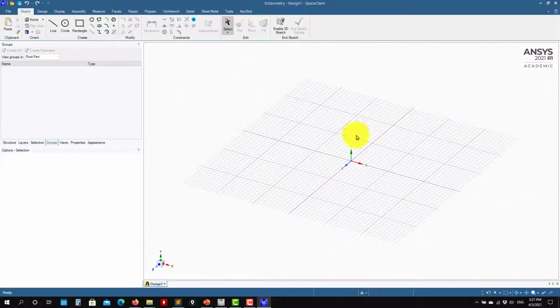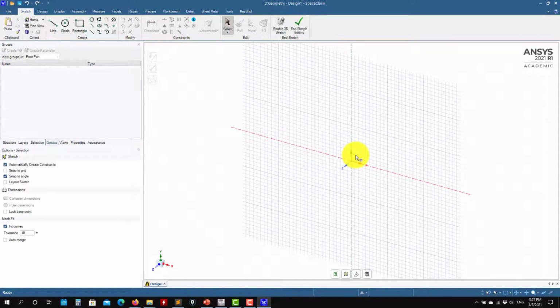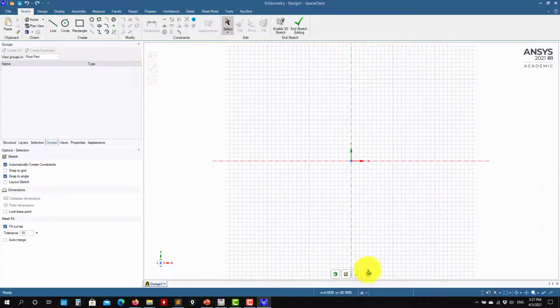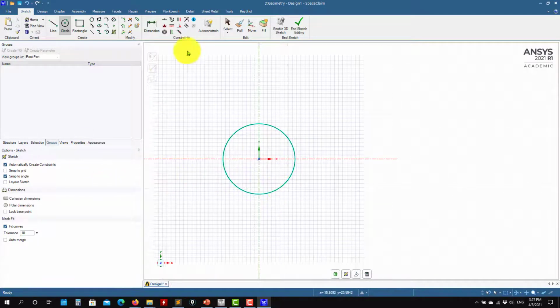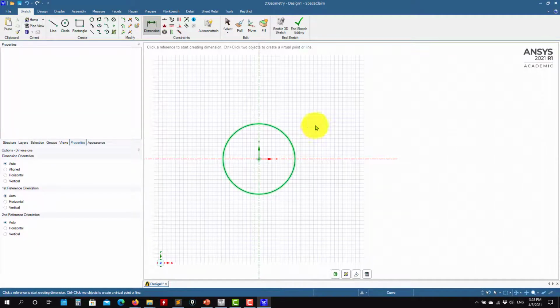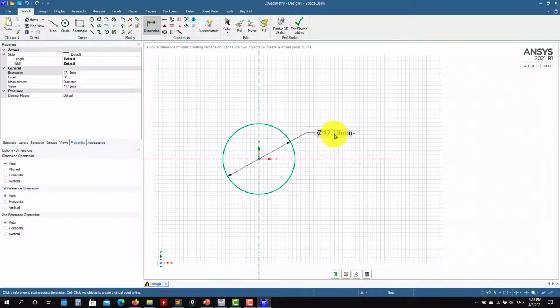So there is a sketch mode, you choose your plane. So I like to do 2D in this plane, normal to screen. And let's draw the geometry. So first we have the circle, I want it centered, okay. There we can put it. So we can add dimensions. So let's put everything here. Okay, so it's using millimeters.